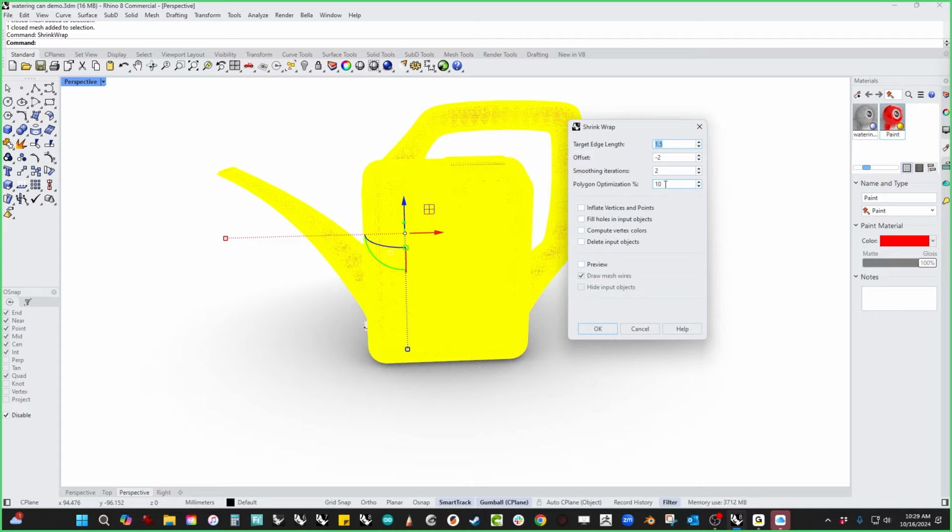And then the smoothing operations, because it's voxels and voxels are kind of cube shaped, what it does is it looks for areas of high curvature and it puts smaller cubes in those areas to make for a smoother area. So if you've got a lot of detail and you're starting to see jaggedy artifacts, put a smoothing operation or 2 or 3 on it. Go easy. This tops out, I think, at about 5 or maybe 10, but 1 or 2 is usually plenty.